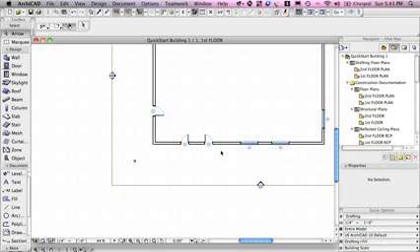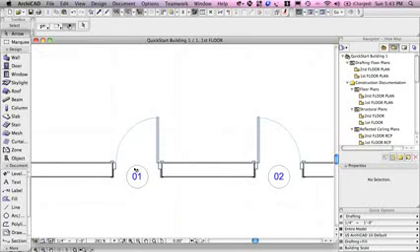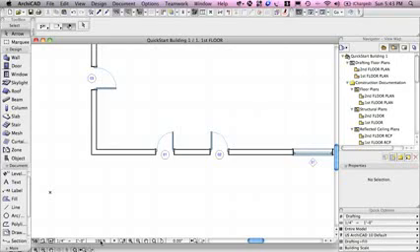But the information in terms of the markers, for example, the door and window markers, and this is just one style, but the size of the text and the size of the circles or other markers are based on the printing scale. So we'll be looking at that, of course, in much more detail later. But if I click on this percentage, this puts it approximately at the real-world size of the paper printing when it's at 1/4 inch, which would be about 1:50.